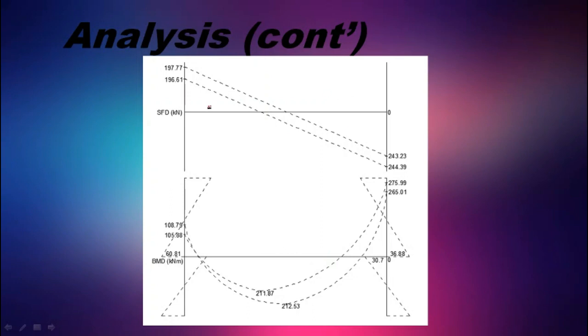From the reactions that were obtained before, we will have to draw our shear force diagram using obtained and given data. After that, interpolating the shape's value gives us the distance of the crossing shear force line. To construct the bending moment diagram, we have to calculate the area of each shape in the shear force diagram. Don't forget to consider the moment of the starting point that was obtained using the moment distribution method. So we will get this value. Repeat the action for both cases and get the full result.